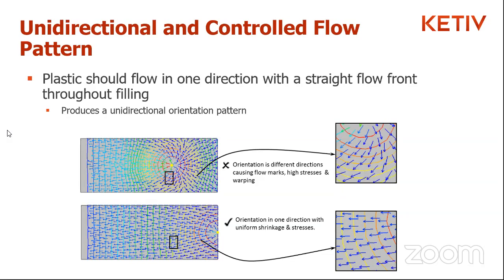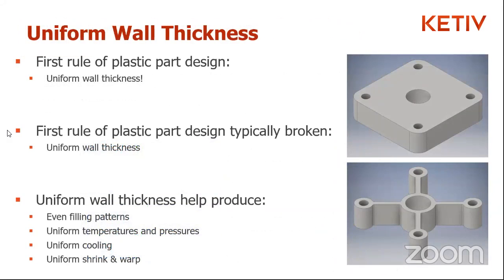Yeah, I think that wall thickness is an interesting guideline, because as you pointed out, we then apply draft, which then breaks that guideline. And I guess one thing to keep in mind is guidelines are always broken. It's just a matter of how severely we can get away with breaking them, and that's truly where simulation comes in, to be that referee, if you will.